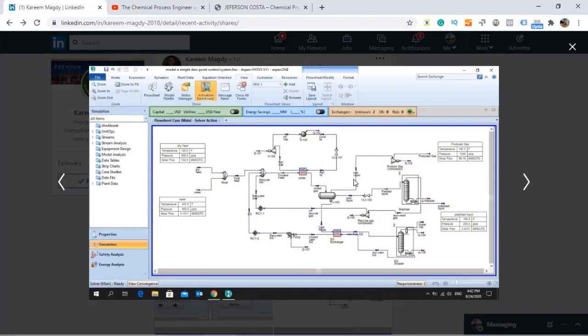And what he said is that the dew point is controlled at the outlet of the separator vessel. And it is true, since we don't change the composition of the gas from the inlet to the outlet of the compressor, the dew point will stay the same. So if at this point here the gas complies with the requirement at the discharge of the compressor, it will comply also, and keep in mind that you always need to comply with the requirements of your process at the fence or the battery limit with your customer.